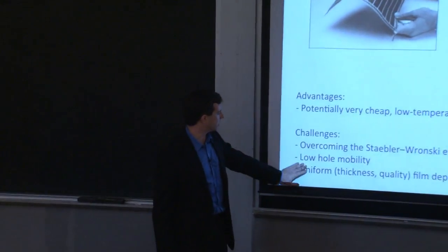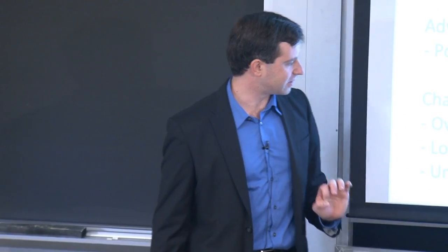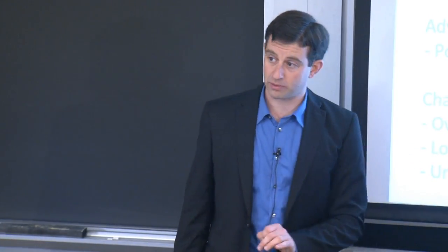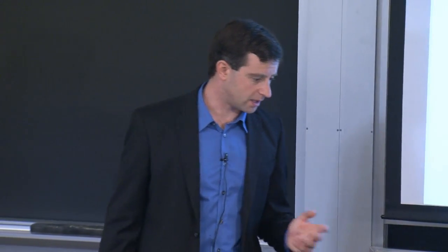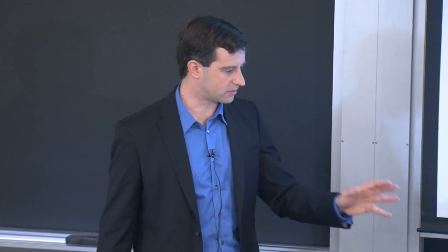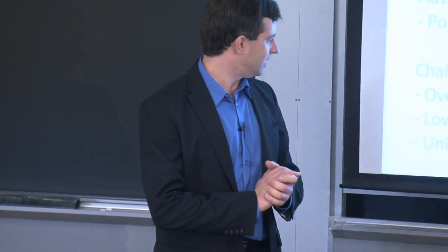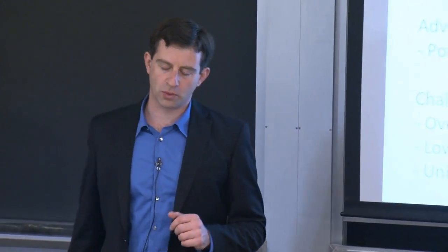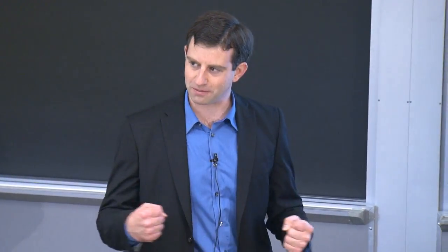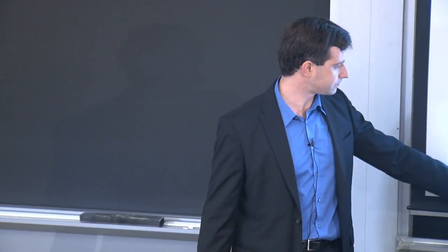In general, amorphous silicon has low hole mobility. Again, the precise root cause on an atomic scale for the low hole mobility is still up for some debate. There's a professor here at MIT, Jeff Grossman, who has performed a combination of molecular dynamics and density functional theory to obtain amorphous silicon samples in DFT. And through those samples, he and his colleagues were able to determine that the low hole mobility might be caused by stretched bonds, certain types of stretched bonds within the amorphous silicon. There are other hypotheses out there as well in the literature.